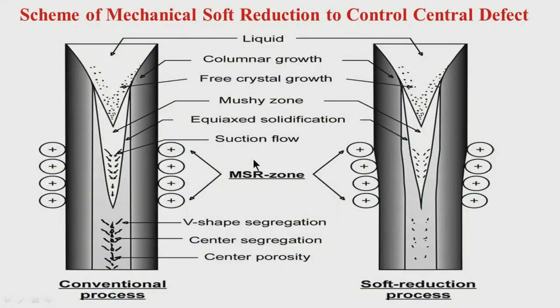You may have manganese, you may have some silicon, you will have some amount of maybe other alloying elements. You may have titanium, small amounts of chromium, small amounts of molybdenum, small amounts of nickel. So, for all these elements there is a possibility of some segregation, and as I have told you, the amount of segregation is more towards the end of the solidification.